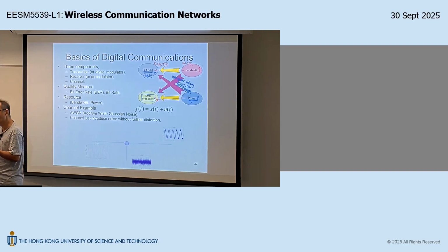Okay? So overall, the received signal-to-noise ratio for 16 PSK may be higher than that of 16 QAM because of the different back-off consideration. Is that okay? So how important this is really depends on how nonlinear your power amplifier would be, okay? So that would be the practical consideration.